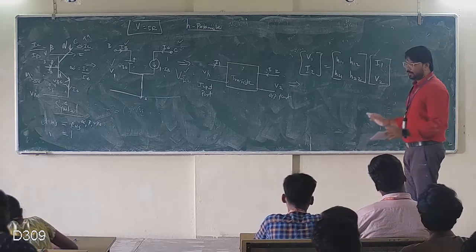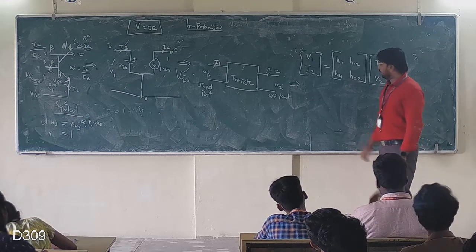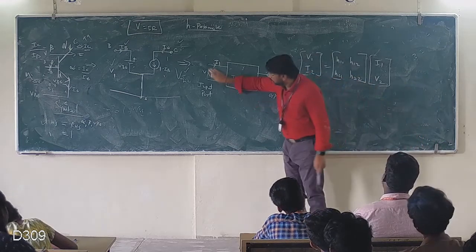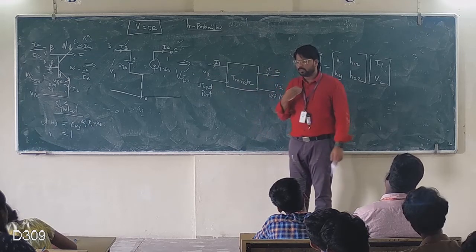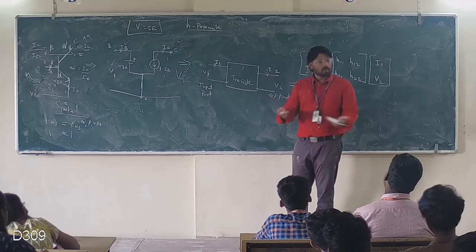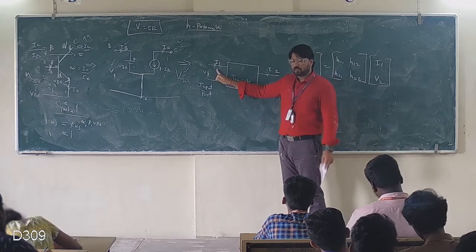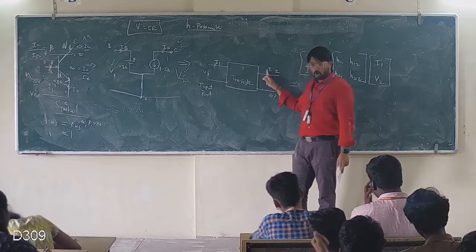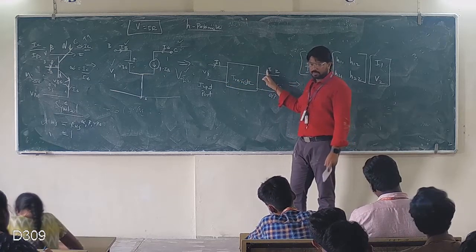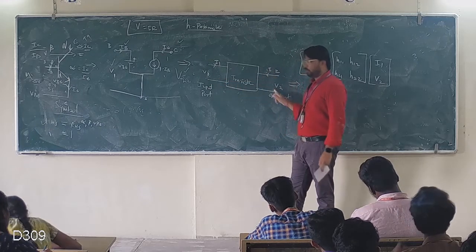Now I model into matrix, right? So what is V1? Input voltage, my voice, weak voice, where? At mic. V2, loudspeaker. I1, weak signal, microamps. I2, strong current, 99% collector current. So VBE, IB, IC, VCE.